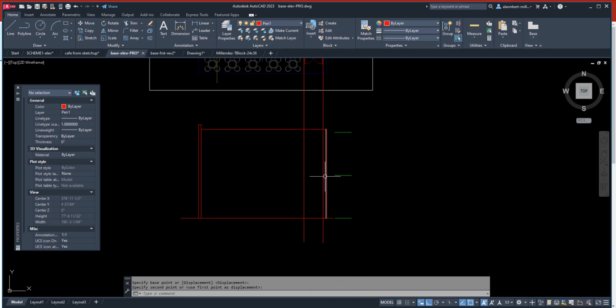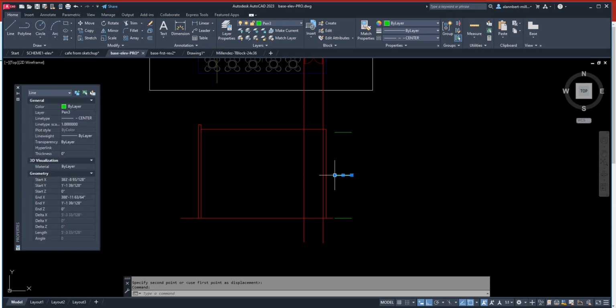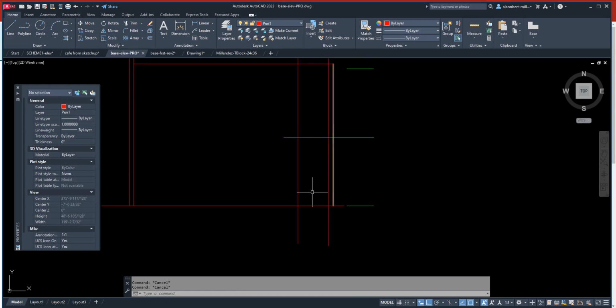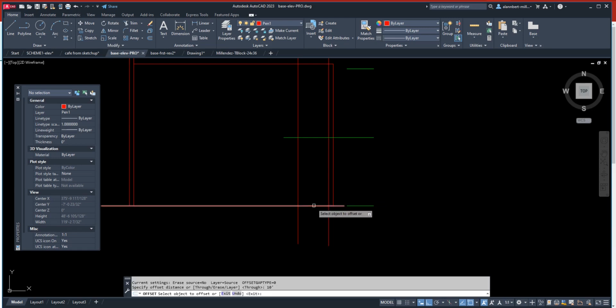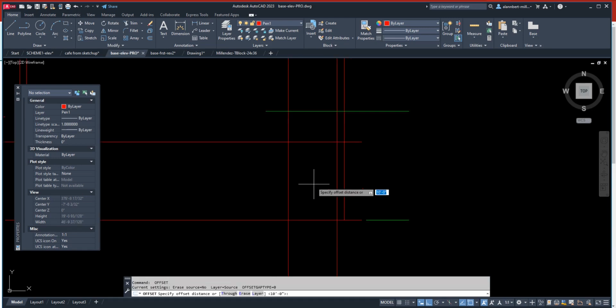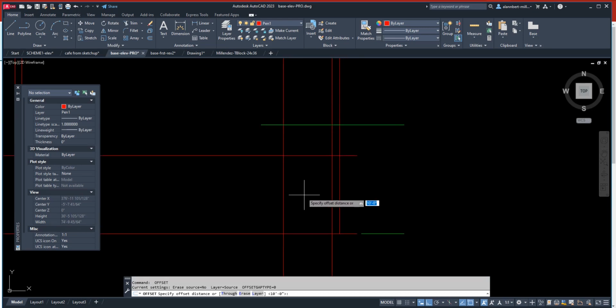Okay, so since this is the level of the second floor, you can bring it inside and you have to decide now, all right, how tall is my front door? So if you want it 10 feet, then just offset 10 feet. Doors are actually just around 6'8" or 7 feet. So we're gonna do another offset of 7 feet.